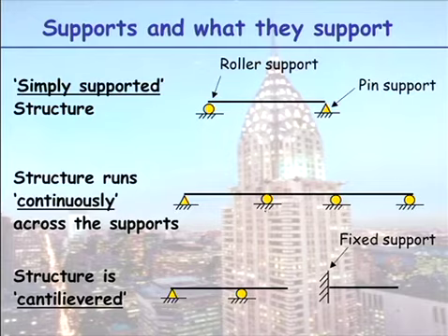So at this point here, you would just have unknown vertical reactions. When, however, we look at what's happening within the beam, there is still an internal moment there. Just remember that when we get to bending. People think, oh, it's a pin support, there's no moment there. There's no moment reaction there, but within the beam there is an internal moment.